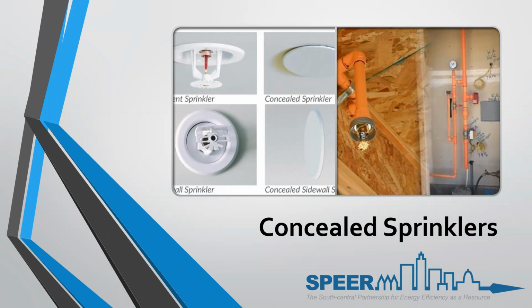There are, what I've seen, gaskets on the caps that don't adhere to the sheetrock that can be installed, but most manufacturers don't sell them. It's an aftermarket and they don't recommend it because they didn't approve it. So there's a way that you can seal it. You can build boxes around them like you do existing retrofit of can lights. You can put a box around it and air seal all that to the sheetrock to lessen the leakage points around that.